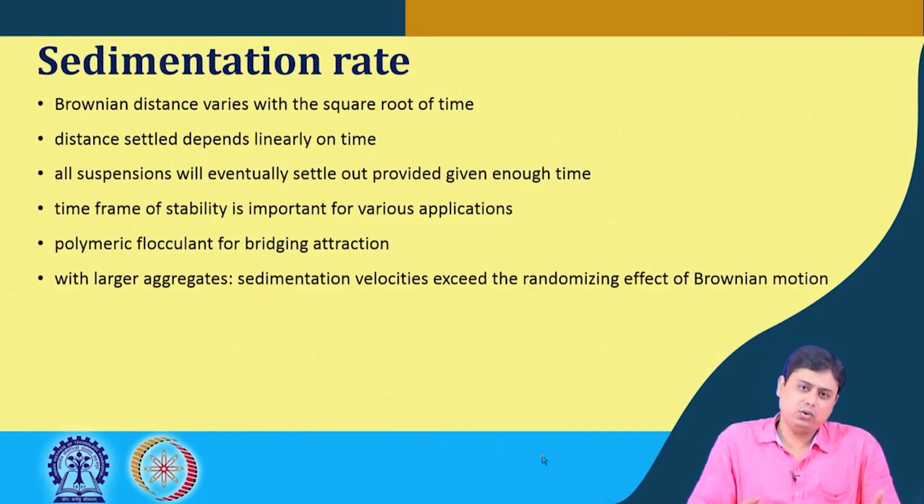So, if you want gravity settling, it is the typical flocculant that we add, which creates aggregates, and again the mass or the size of the particle increases. So, size enlargement happens. As it increases, the sedimentation velocity increases, or the body forces increase, which overcomes the surface forces, and then we can have the gravity settling.